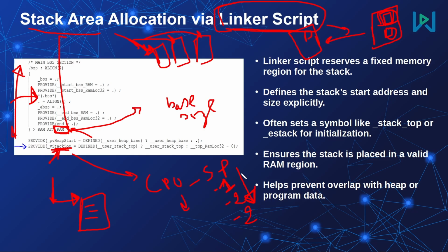And by the way, this direction of our stack pointer is supported by most of the modern processor architectures like the Cortex-M and RISC-V. So here, each time we push a new element, the stack pointer will be decrementing by the size of that element. And if we pop that element, then the stack pointer will increment by the size of the element that has been popped.